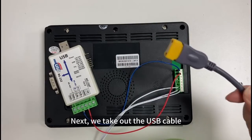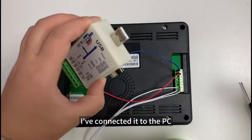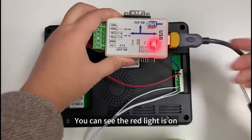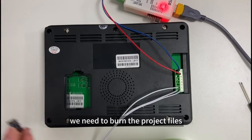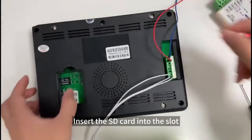Next, we take out the USB cable. On the other end, I've connected it to the PC. This end is used to connect the adapter board. You can see the red light is on. That means our connection is successful. Next, we need to burn the project files. Insert the SD card into the slot.